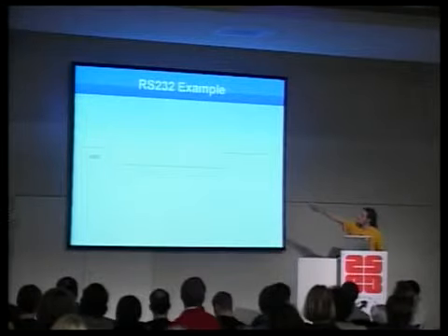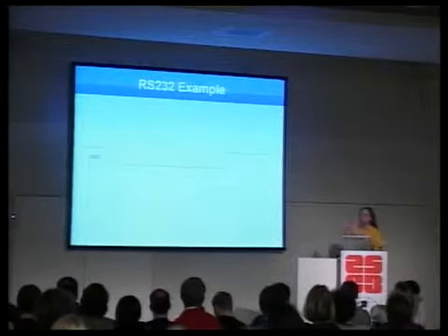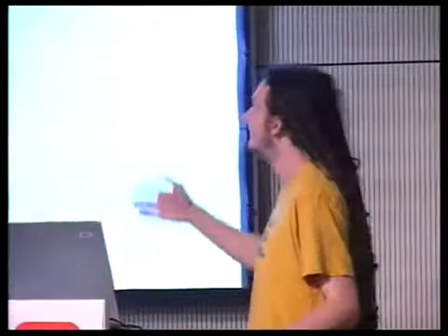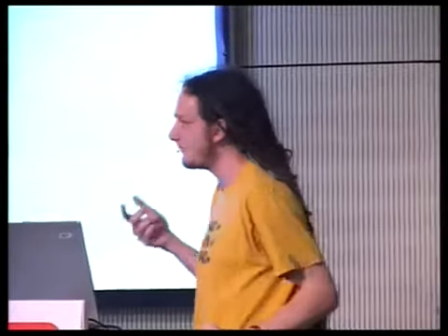Think of the message as a difference between the 2 edges. If you divide that by 8, you get the width of 1 bit. So that's what it does. It starts its own timer by measuring the difference between these 2 edges, and that's how it knows how quickly to speak to you. As long as you don't overrun or underrun this counter, you can choose any odd baud rate that you like.